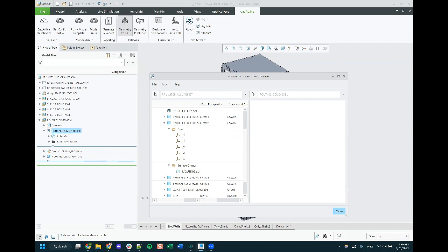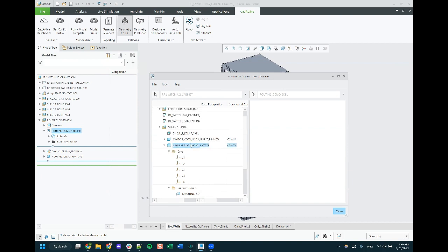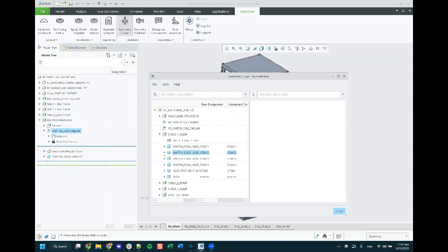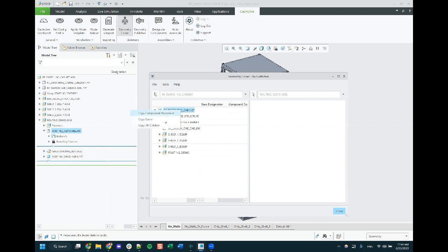Now, because I have these published geometries, I can create a copy geometry of this individual coordinate system. I can choose the entire group of coordinate systems. I can do this from the part level, or from the assembly level. To really show where we could get this in the finalized state, I'm going to go to the top level of my assembly, and I'm going to assume that all of our models are set up with published geometries that are thought out at the library part level.